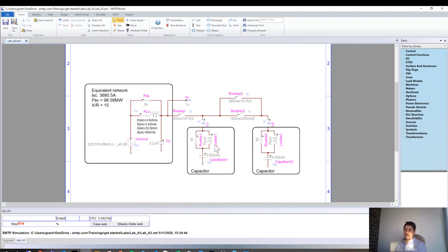Now you have a voltage difference of 2 per unit across this breaker. So the overvoltage will be even worse. Why would you do that? Of course, you never do that. Well, you don't re-energize the cap bank before it's discharged, and so you have resistance to discharge.